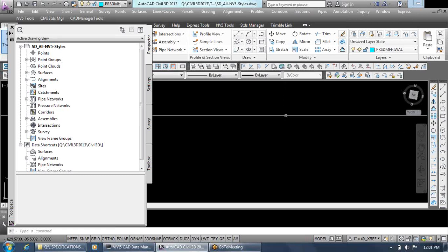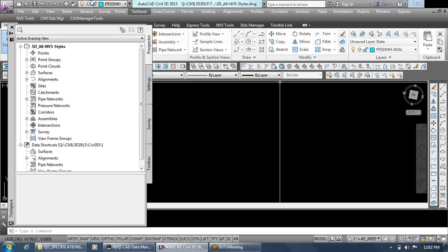And then the last thing, kind of on that same subject, is whenever you get a recover file, make sure if you're not going to use it that you delete it out from your folder. Anytime you go to File Open, it should just be a list of drawing files that you're currently using. So anything with the recovery behind it, any autosave after a crash that gets put into your folder, be sure to just clean that up a little bit.